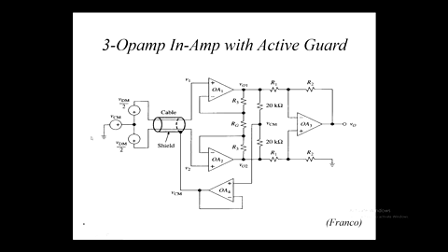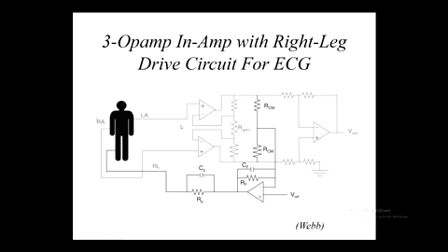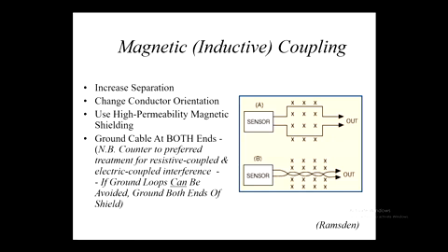In this case, common mode signal is being placed on the shield so that it will reduce the amount of interference signal that's induced into the signal cables, because once again, if you've got two points at the same voltage, then no current will flow between them. So it intercepts interfering signals that way.